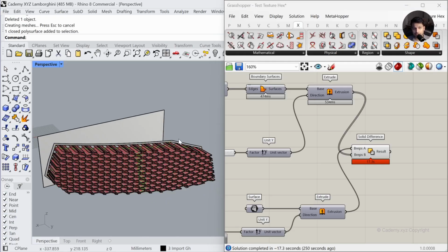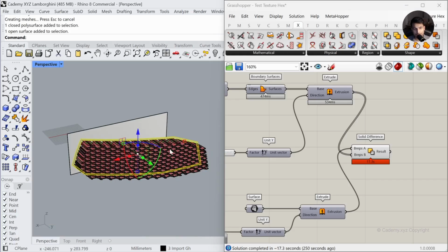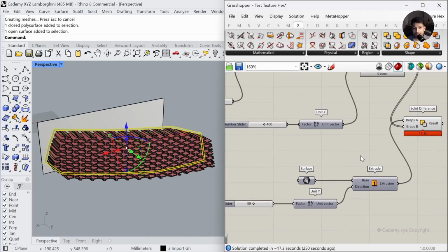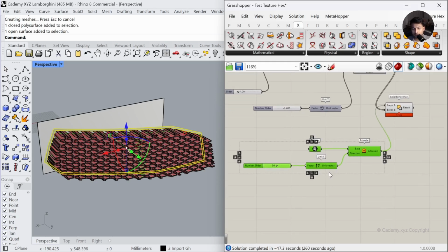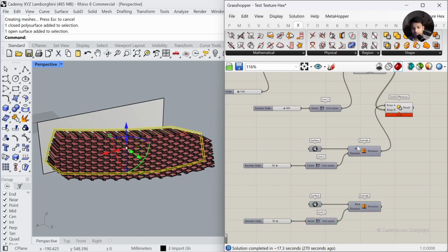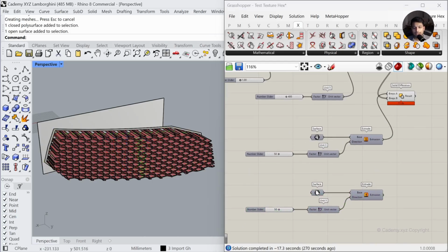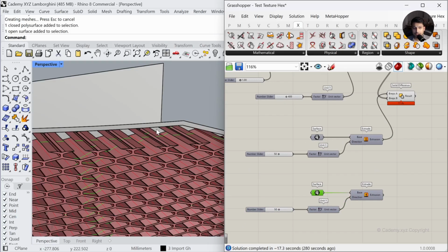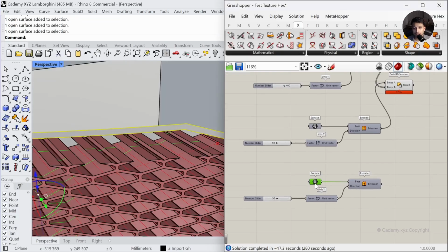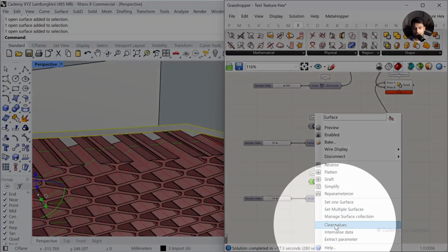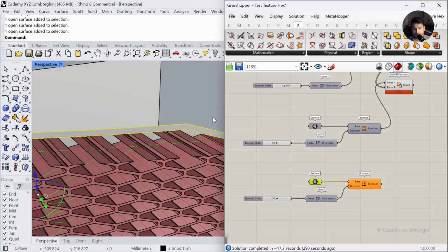The next step is to extrude this skin surface, okay, of the exhaust. So I have to recreate a similar configuration where we import the surface, extrude it by some amount. Now, rather than recreating it, you can select these nodes, okay, Control C, Control V, and we have created a copy of the entire script, okay? And rather than importing the original surface, the one that we had here, we are going to import this one instead. So first, let me clear the values to delete anything that was inside of the previous container.